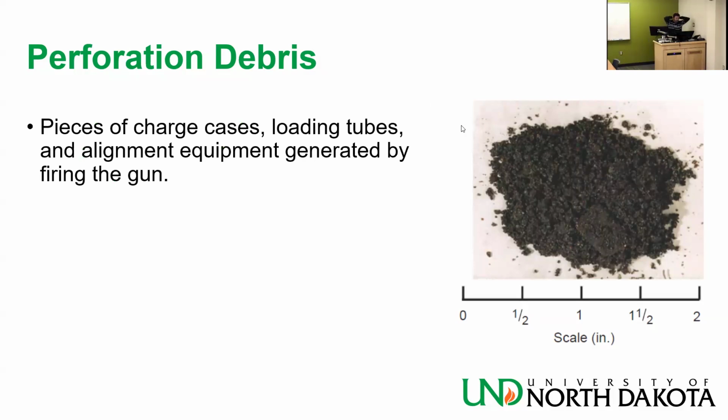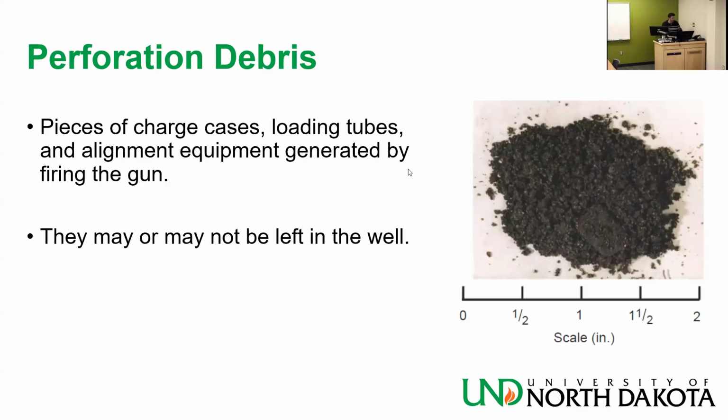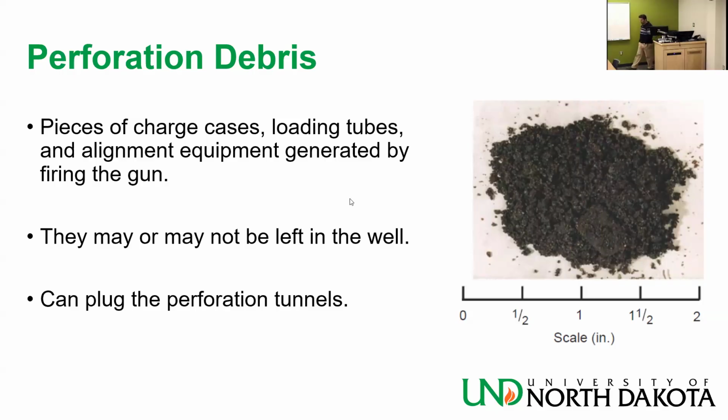Pieces of charge cases, loading tubes, and alignment equipment are generated by the firing gun and can be debris. They may or may not be left inside the well, and can plug the perforation tunnels. Then you need a job called an acid wash to clean them up before starting the fracture treatment, which is a very common situation in the US.